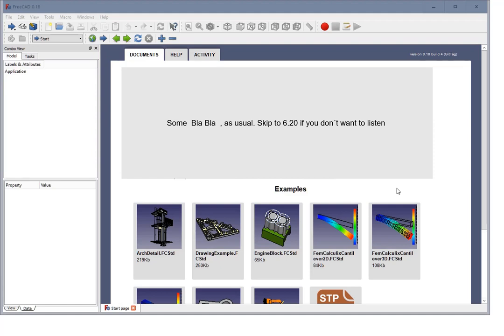The problem is still that when you use the formula editor, which I do very often, and you want to refer to any value that has been defined inside FreeCAD, or you have defined as a named constraint or as a value in a feature distance or whatever, you have no suggestions on the name.